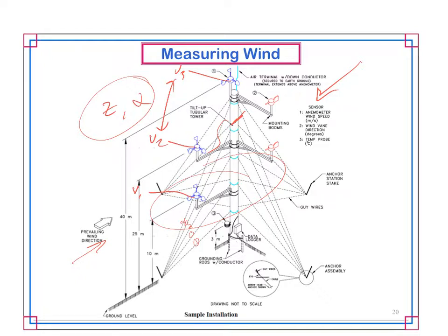Okay? This also shows you a couple of wind directions, right? So did I get the prevailing wind direction correctly? Because locating the tower, as we learn, or locating the wind farm, it's important to try to face the turbines in the prevailing wind direction. The larger commercial ones will auto adjust to be in line with each other, but if you have more than one turbine, you want to make sure that they're spaced in a way to minimize the impact